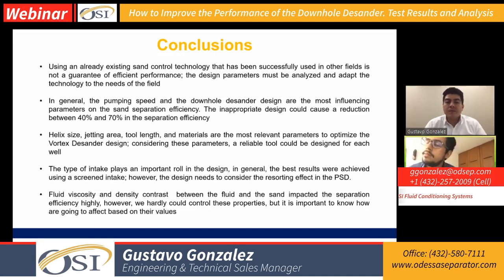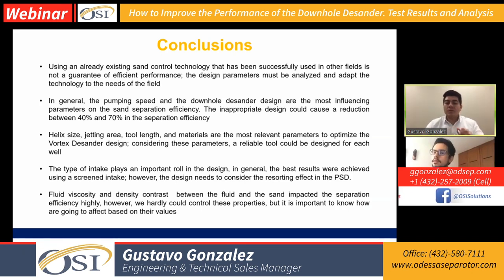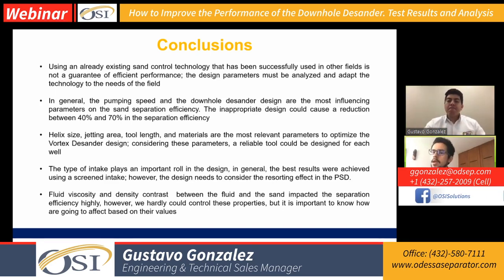Another really relevant conclusion that we can get from this analysis is that inlet size, jetting area, tool length, and the materials are the most relevant parameters to optimize the design of the vortex desander. If you consider these parameters in your design, you can have a really, really reliable tool downhole.